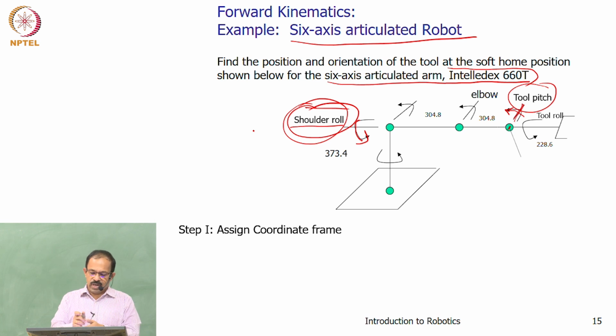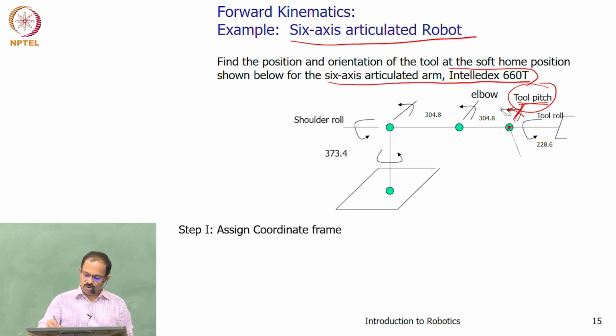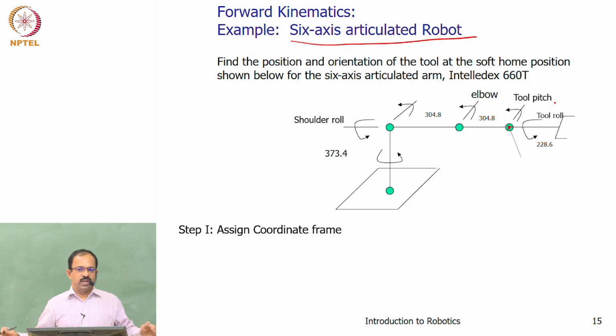So basically, you are having two roll axes and in between a pitch axis. So you will still be able to control the yaw, because we have an additional roll here which can position it, so you can control the yaw using this joint. So effectively, it has got all the 6 degrees of freedom. So it's actually an ergonomic one.